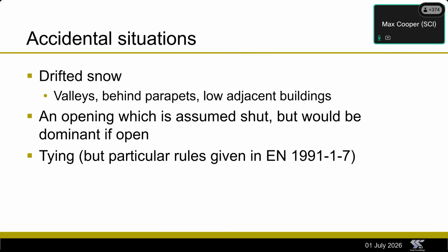The final one is tying. We'll go into a bit more detail later, and these are combinations where we want to avoid the disproportionate collapse of a building due to an accidental action. And there are particular rules given for the load combinations in EN 1991 Part 1-7.